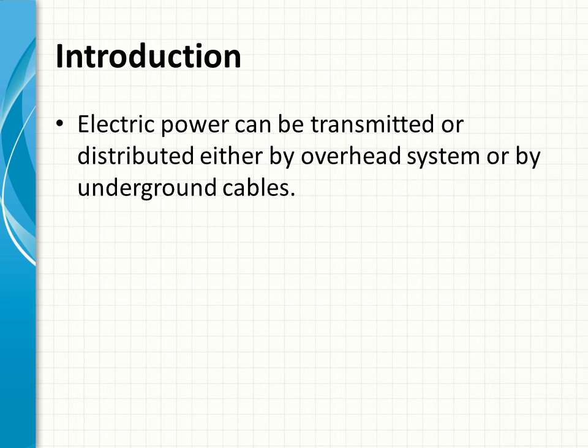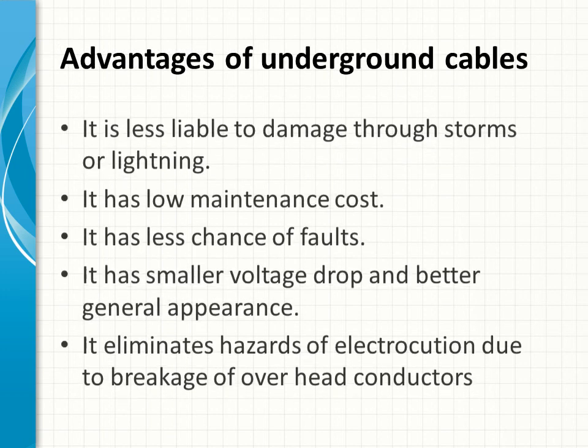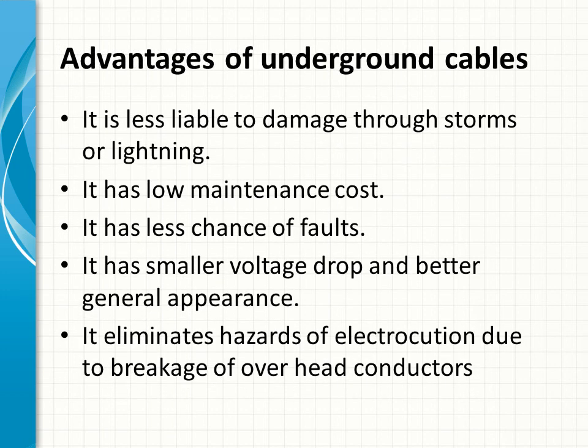So next, let us look at the advantages of underground cables. These are benefits that are associated with laying electric cables underground. Number one, underground cables are less liable to damage through storm or lightning. Here in this case, by digging out trenches around 2 meters, tunnels are constructed through which the cables are passed.